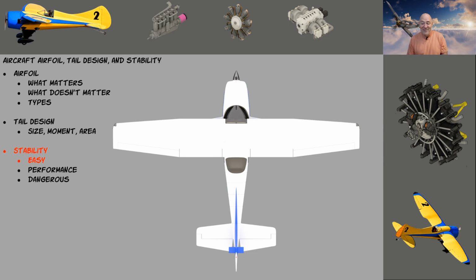I'm not making fun of anybody. But I've test flown a lot of airplanes, and the person says, this plane is really, really hard to fly. Once I set up the throws, put a little bit of exponential in it, might have to change a little bit of, you got your horn on your elevator or aileron or rudder.